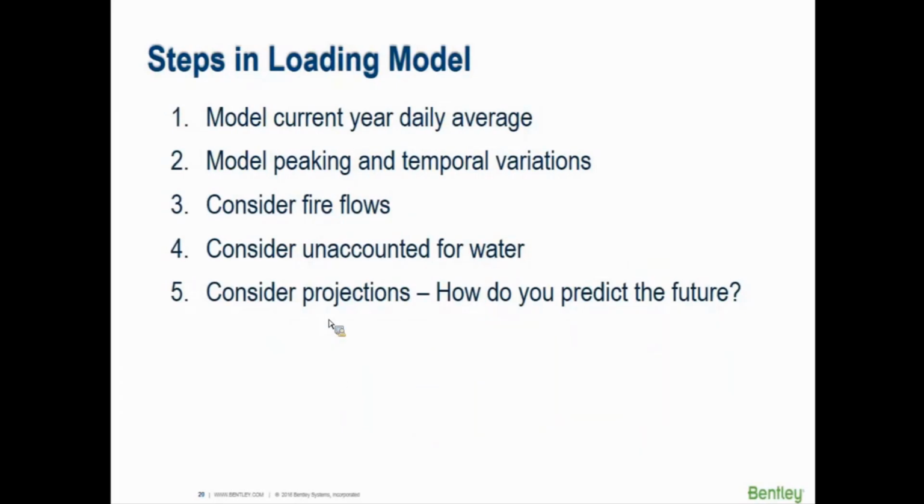As you load the model, are you going to load it for current year, current average data? What type of peaking factors are you going to apply to get it to be able to model the maximum day? Are you going to consider fire flows? How many fire flows? Are you going to consider unaccounted for water? And what percentage is that going to be?